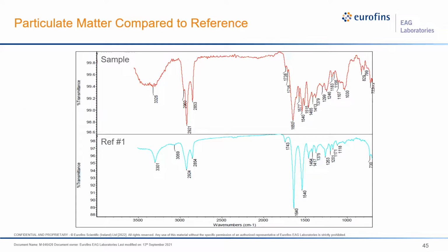And of course, we have a spectrum on top. This is for the 4 millimeter stiff sample, and the bottom is the client-provided polyamide reference. We think it's a relatively okay match, but there's something a little concerning: some characteristic bands in the sample that are not in the reference material. One is around the 1,000 to 1,100 range. We don't really see a significant amount here.